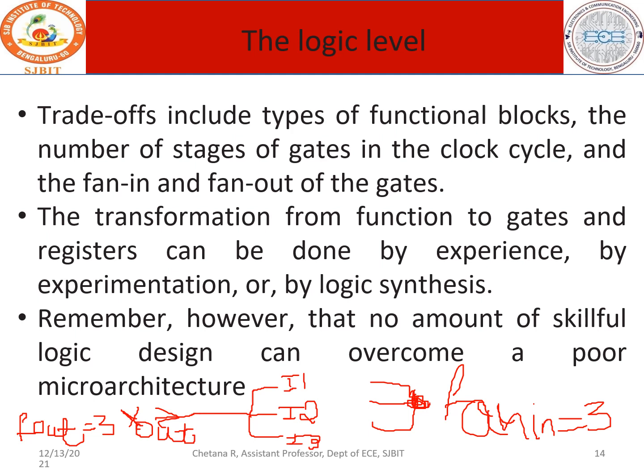The transformation from function, so we are talking in terms of the functional block or the number of stages, to gates and registers can be done. How will you consider that this is going to create a delay? This is simple. It is calculated in terms of the experience of a person. He or she will know that if you have this much fan in and this much fan out, the device is going to experience a delay. Or by experiment or by synthesis, you have to generate, run and see.